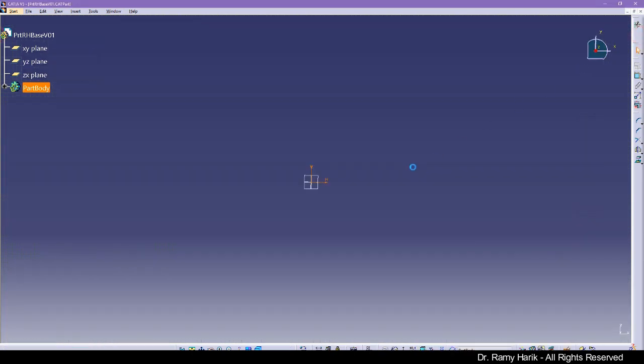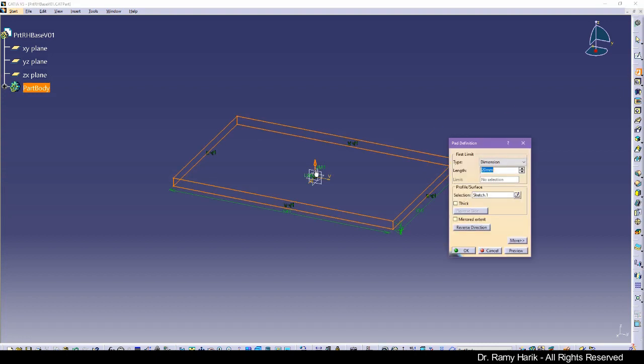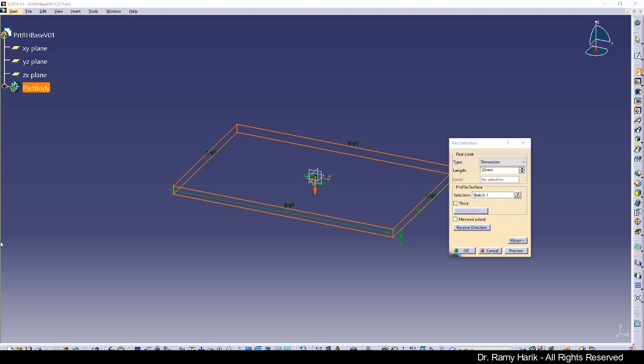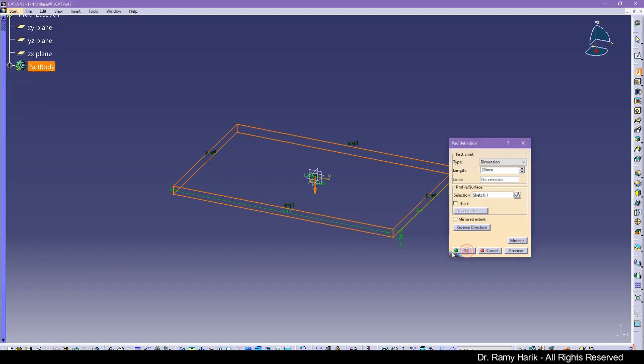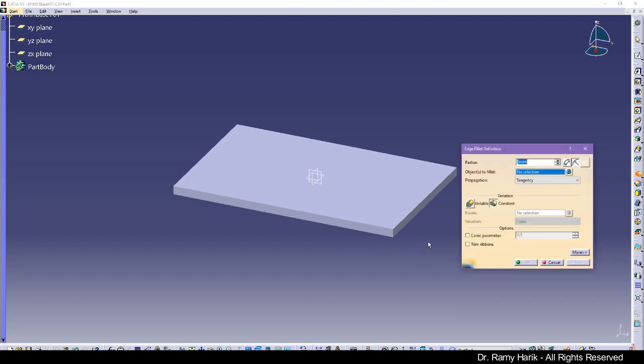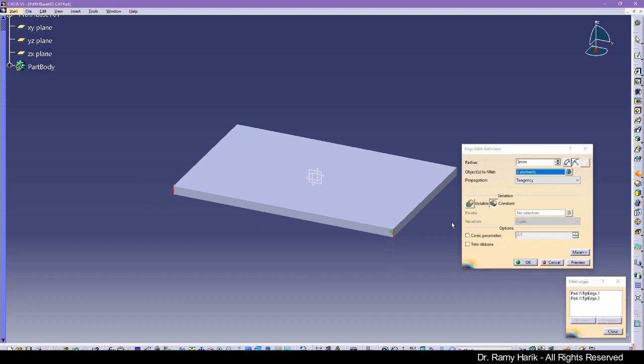And we close that. So the way that I'm going to extrude is towards the bottom. I'm going to use the XY plane as my reference so that I can build on it the other profile. And the dimension here is 20 millimeters. That is good. And it does have a filleted radius of 10. So we're going to press fillet and click here to select several objects. So we're going to do this one. We're going to do this one.